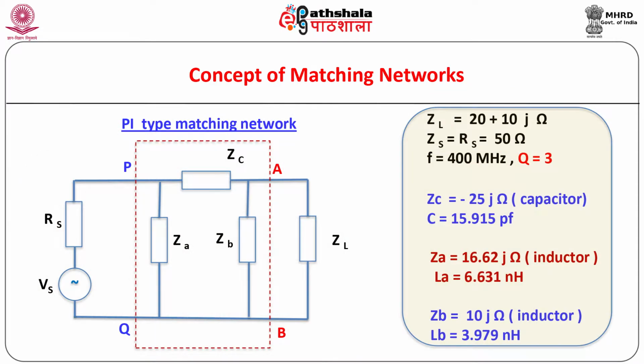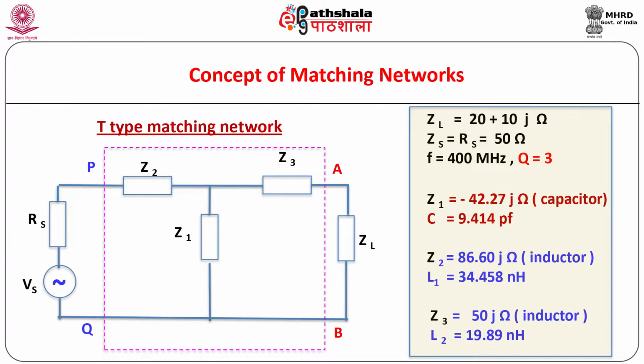We are familiar with the terms star and delta networks, also known as T and pi networks. Let us see the use of these networks as matching networks between source and load. It is to be noted that the two physical quantities, namely source impedance and frequency of the signal, are of direct concern in designing of matching networks. Hence, many a time the source symbol is not shown in the circuit diagram. See the circuit as an example of a pi type of matching network. As an example of a T type of matching network, see the circuit as shown.